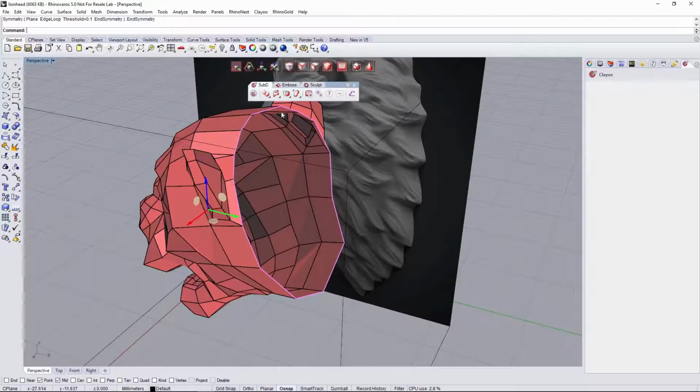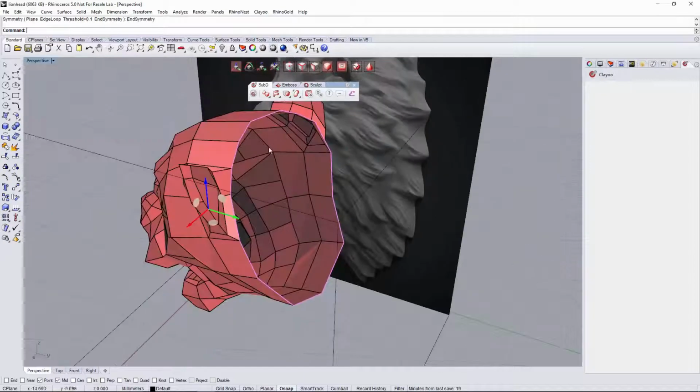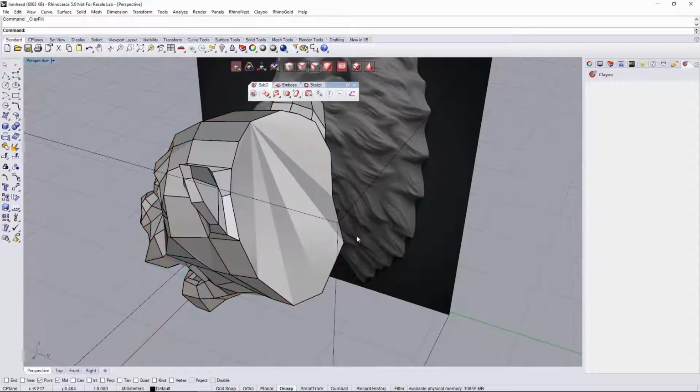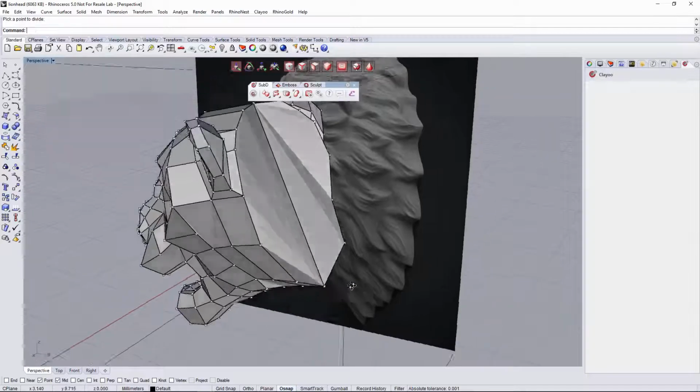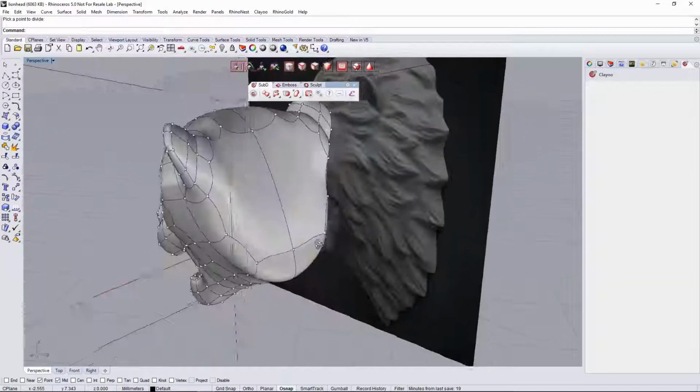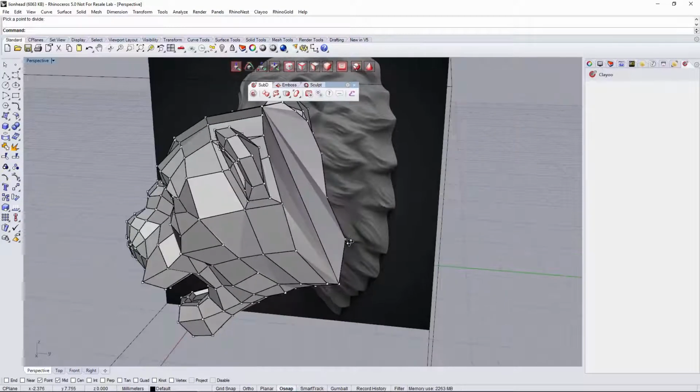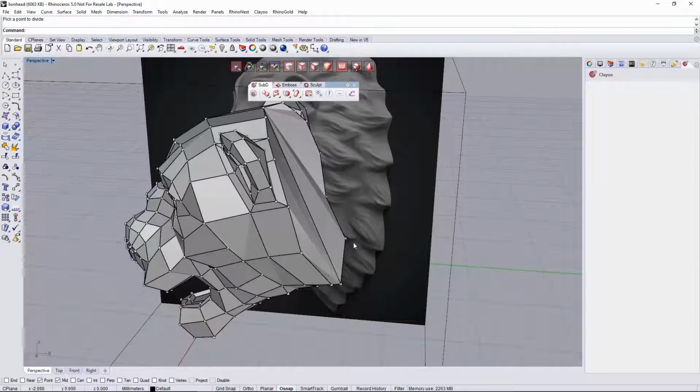So select the entire object, and what I recommend, well, the entire or just the naked loop of edges in here, and go to addition and fill. Okay, this is creating an ngon, so we don't want an ngon, but we're gonna refine it right now. So divide from here to here. This is not planar, so maybe we can make sure that this is perfectly planar.